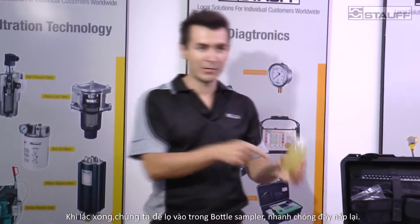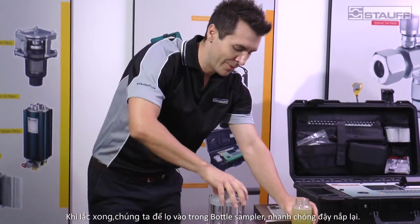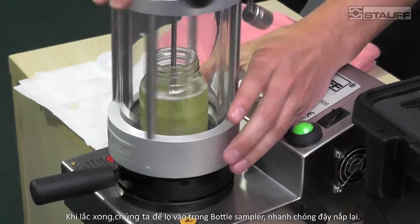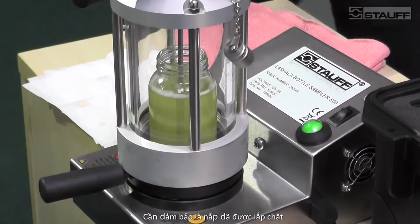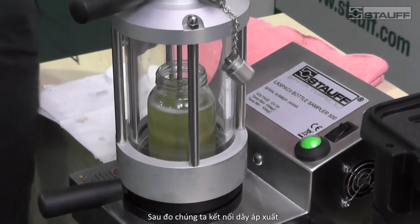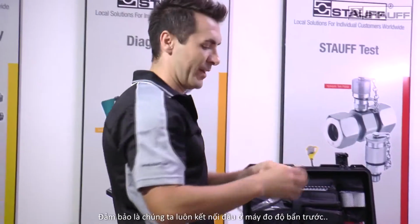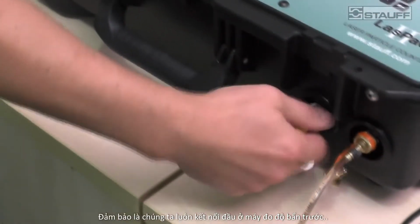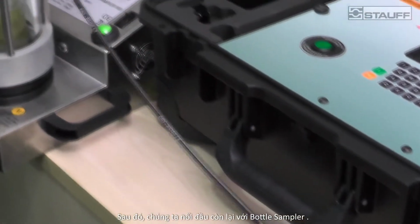And then put the bottle into the bottle sampler, and then very quickly close the lid. Make sure it's closed tight. Okay. So then we connect the hose. Ensure you connect the particle counter first, and then connect the other end to your bottle sampler.